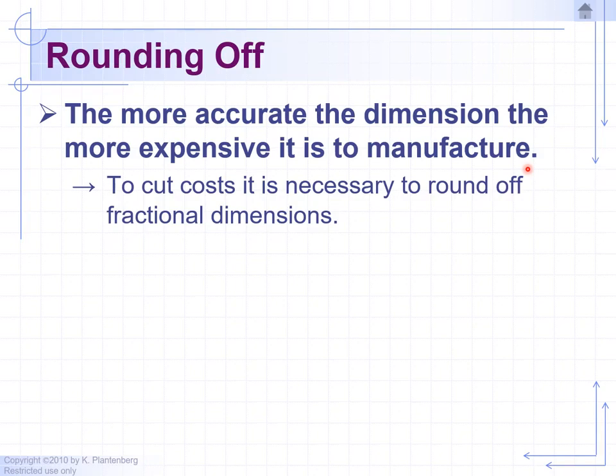If you're using 1 decimal place, like 1.0, then the machinist can go fast, machine the part at a high rate of speed, because accuracy is not important since you're only giving them 1 decimal place, such as 1.0. But if you're giving the machinist 1.000, 3 decimal places, then the machinist has to slow down and take their time to guarantee accuracy.